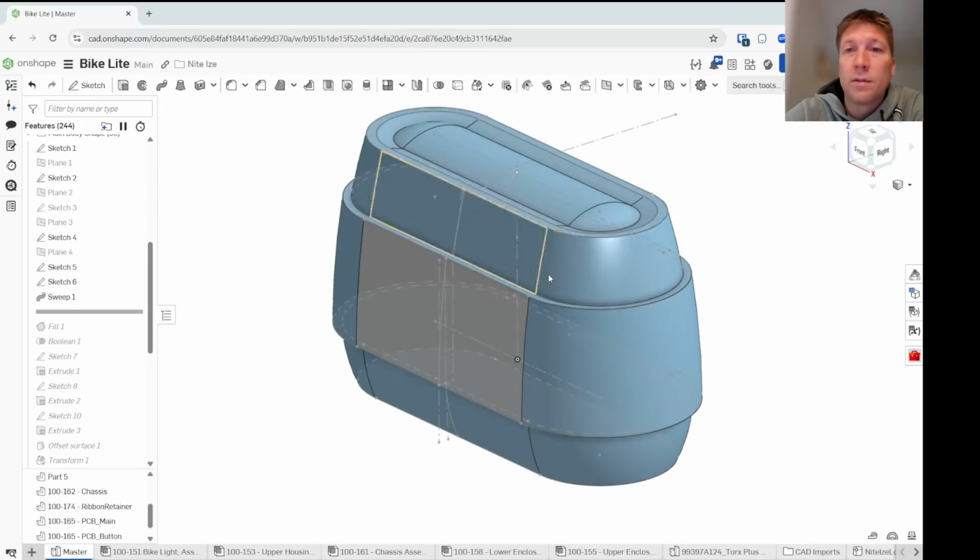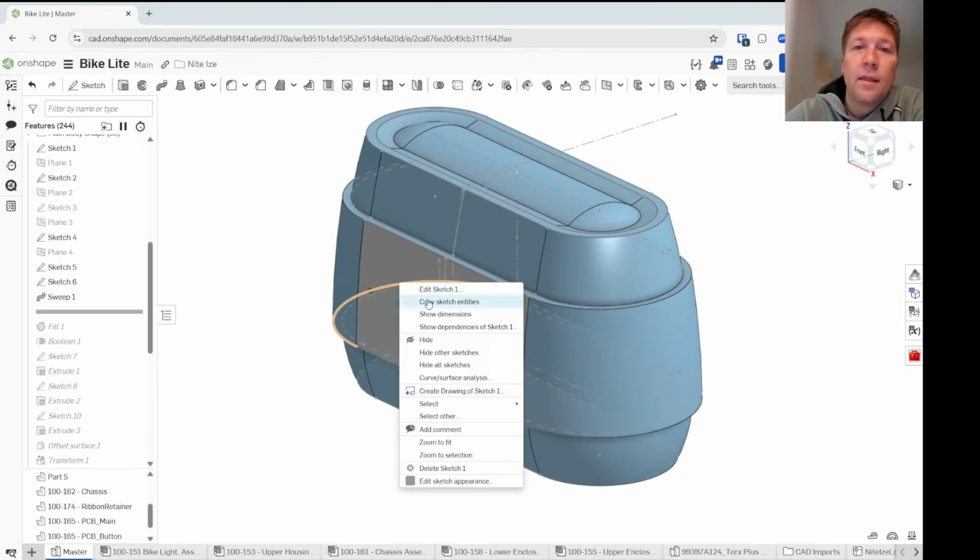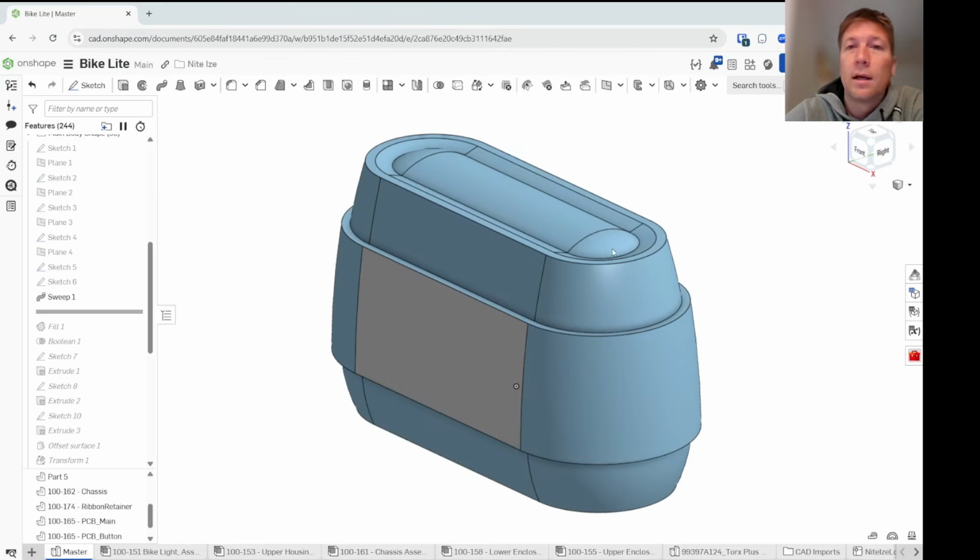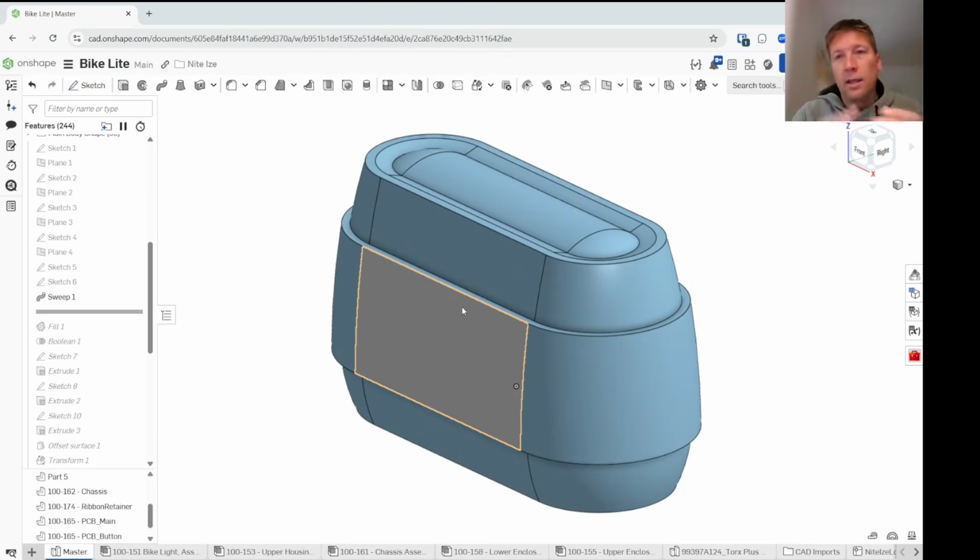Now, since the outside, the A side primary surface, is the most important here, this is what I'm trying to drive. And if I find out after thickening and turning these into parts that there's not enough room inside, I can come back and adjust the A side surface slightly, but I'm not leaving the A side up to chance. If I were to initially draw everything as the B side surface, or the inside of the part, and then thicken it outwards, I don't have control over the A side surface. And so the outside looks kind of like an accident, and we don't want that.